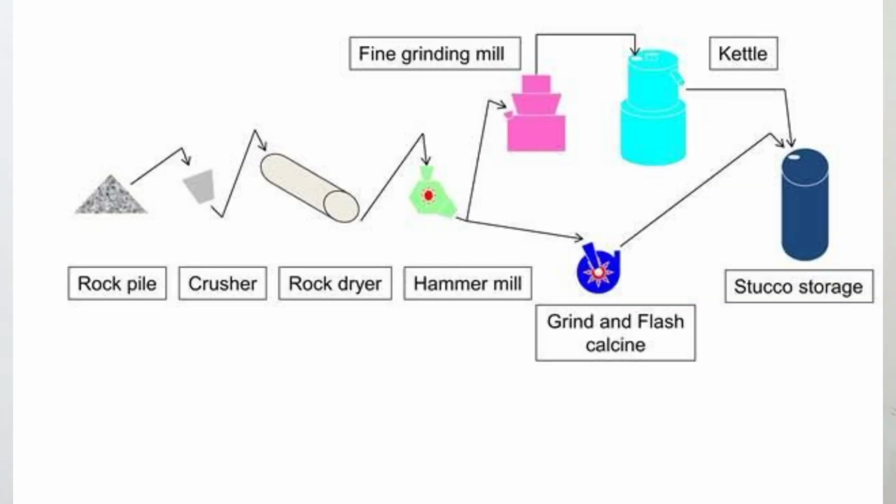First, dry calcination. In dry calcination, first we have to grind the gypsum product into fine particle forms and then place it in open kettle or vessel and then heat it 120 to 180 degrees centigrade to remove water and carbon dioxide from the gypsum. So the process of heating results in the formation of calcium sulphate beta hemihydrate.